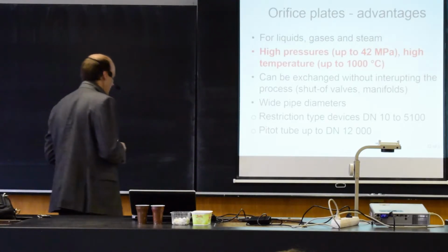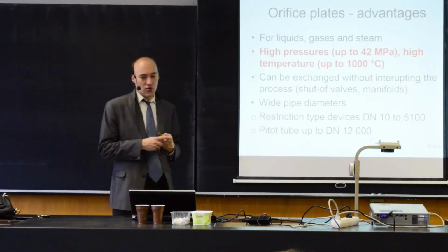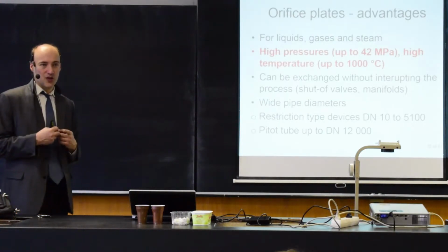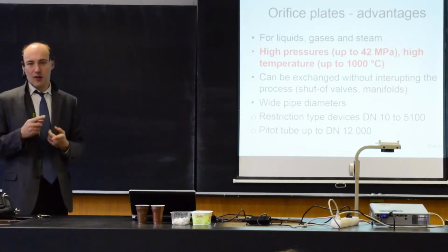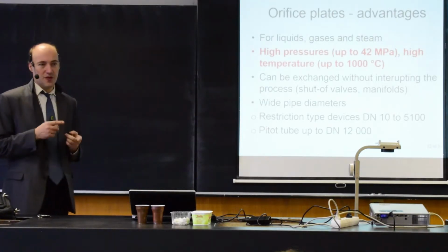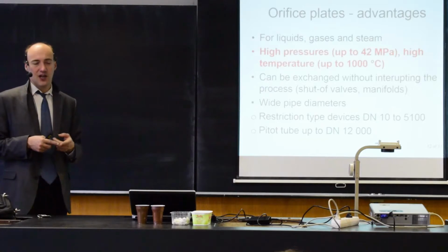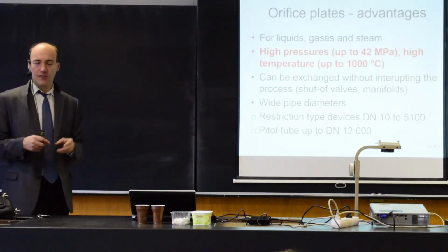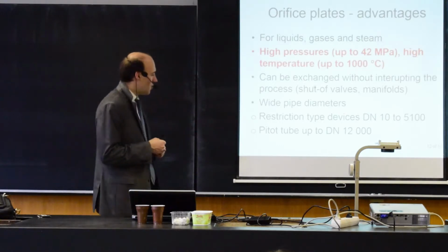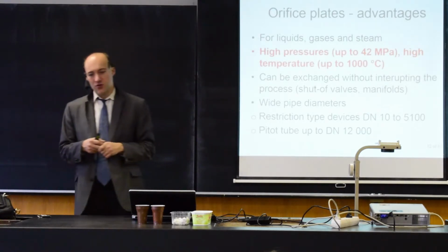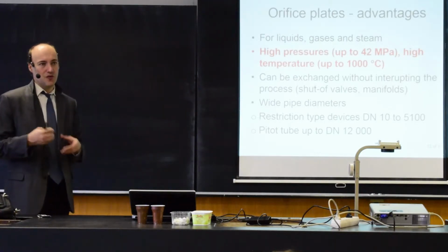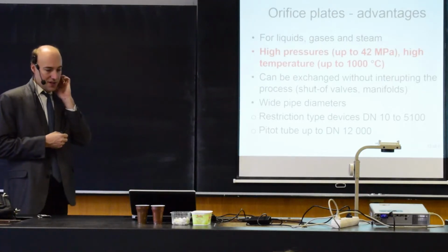If you have the valves installed, you can exchange the orifice plate or the pressure sensor without interrupting the process. So if you just need to exchange the differential pressure gauge itself, you just close the valves, replace that, and close it again. Of course, if you need to replace the orifice plate, you just need to interrupt the process, close it, remove the orifice plate, and replace it.